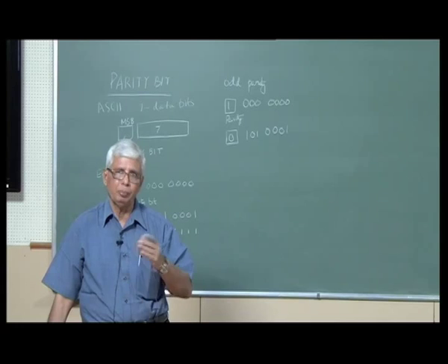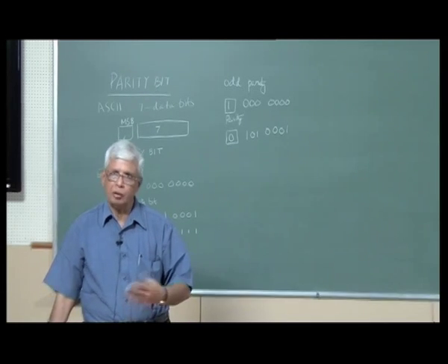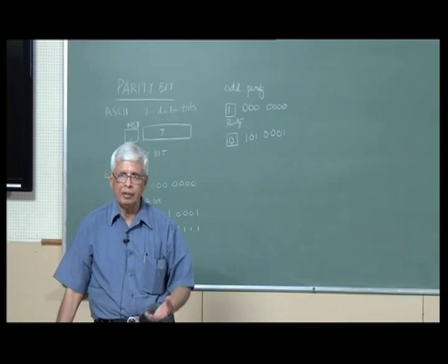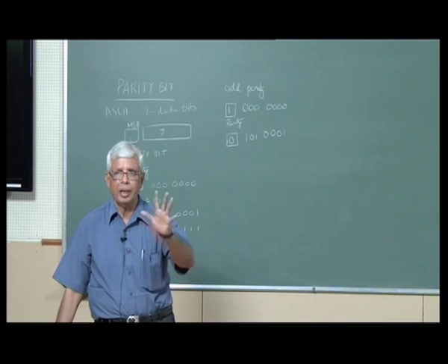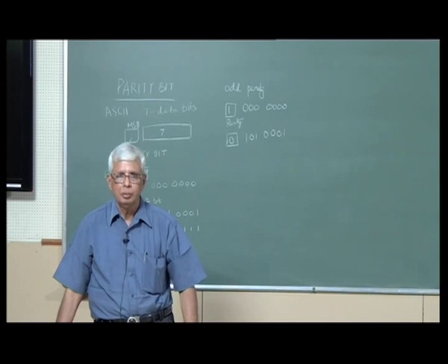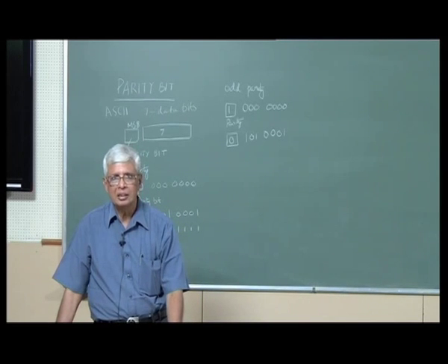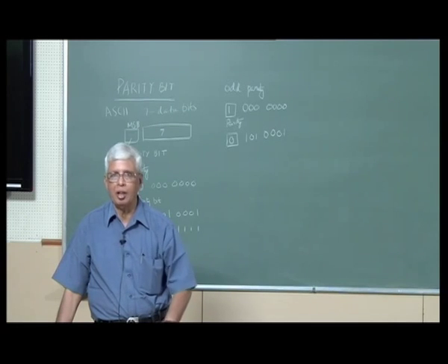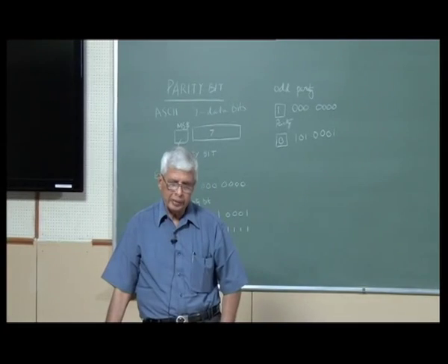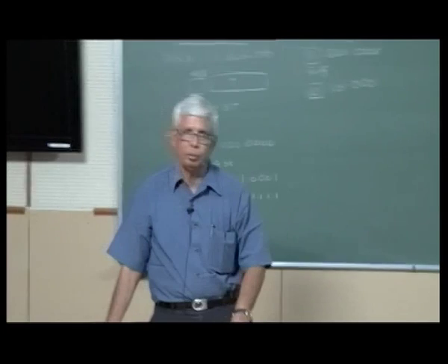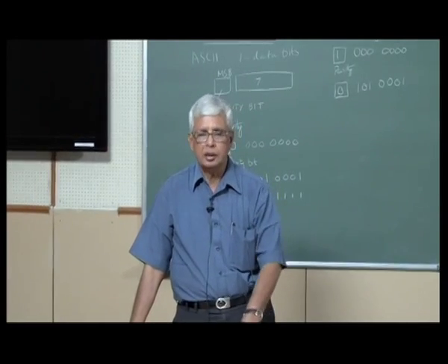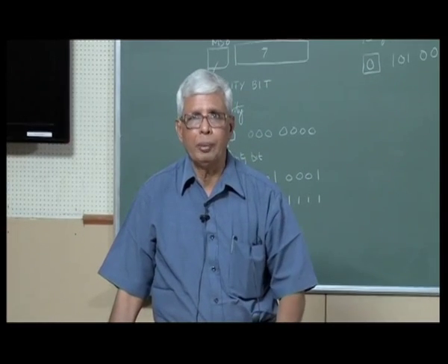You get 7 bits and 1 parity, 15 bits and 1 parity, 4 bits and 1 parity, whatever your data format is, it doesn't matter, because the receiver and sender have synchronized this information already. My data consists of 7-bit words followed by parity, or 15-bit words followed by parity, like that.